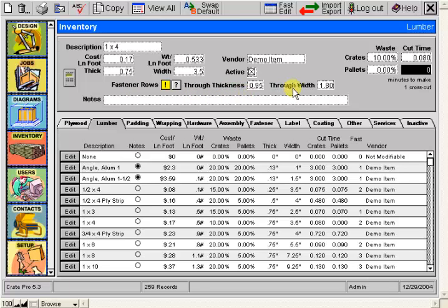Now these fields allow CratePro to calculate a reasonable and consistent number of fasteners at lumber junctions. What's that mean? Well, although these values are used in CratePro, it can best describe them in the context of pallets. In most cases, CratePro designs performance pallets and containers rather than engineered. In this case, that means CratePro will not tell you what the weight capacity is of a given pallet design. Likewise, it won't identify that you should use a ring shank nail versus a straight shank.